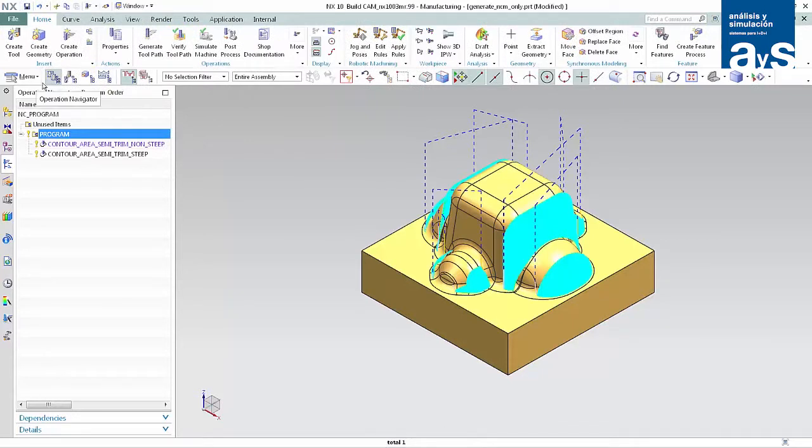By default, the data necessary to perform smart regeneration for each operation is retained only for the current login session. Once you log off, the data is lost and must be again created for each operation. You may, however, specify a customer default that saves this data with the part file. Although this increases the size of the part file, it allows you to continue performing smart regeneration in subsequent sessions.